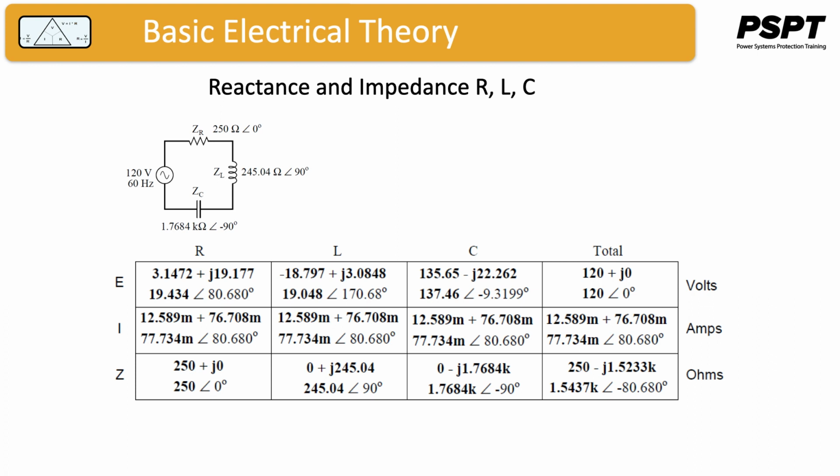Notice something strange here, though. Although our supply voltage is only 120 volts, the voltage across the capacitor is 137.46 volts. So how can this be?